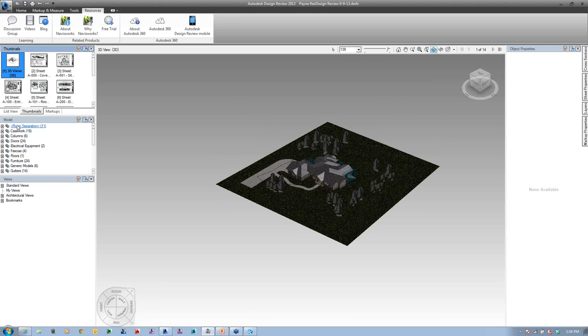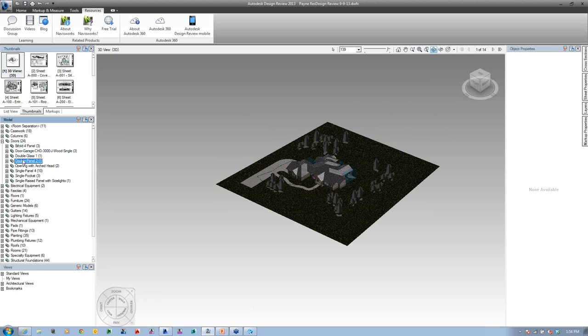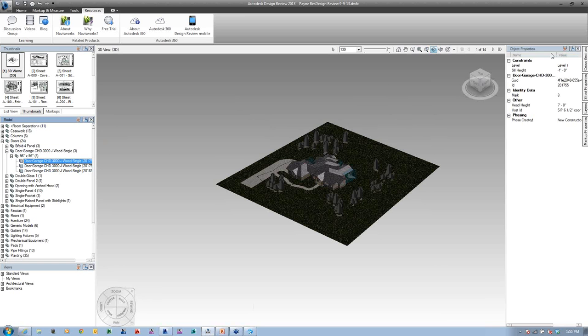Within the 3D model, we can see now I have access to this model tab over here. And like I was saying earlier, I automatically know there's 24 doors in this project that have been added in here. If I hit the plus key, I can start seeing those in here. I can actually select them from this list and start to see that data, or select each individual one and I'll get the information about that individual door. Again, selecting it from the list just like you would select it from the project browser in Revit.